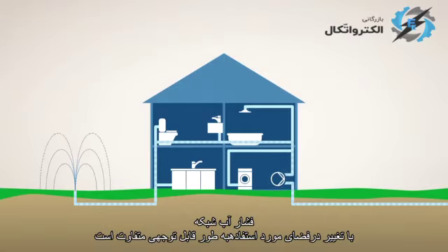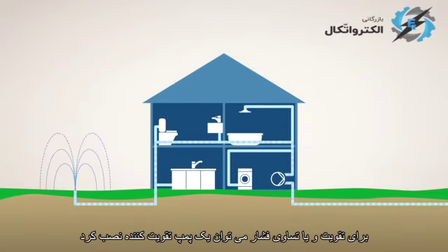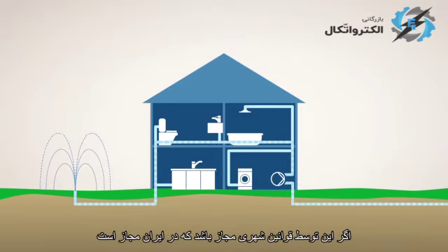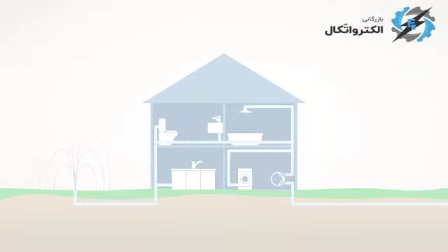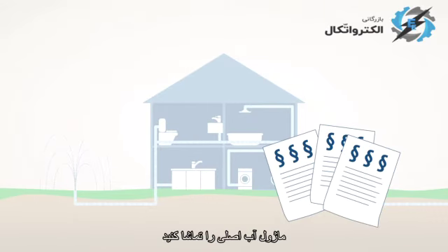Boosting of mains water. The pressure of mains water varies significantly with changes in demand. To stabilize water pressure in the domestic building, a booster pump can be installed to boost and/or equalize pressure, if this is allowed by local legislation. To learn how to select the right pump for the boosting of mains water, watch the mains water module.